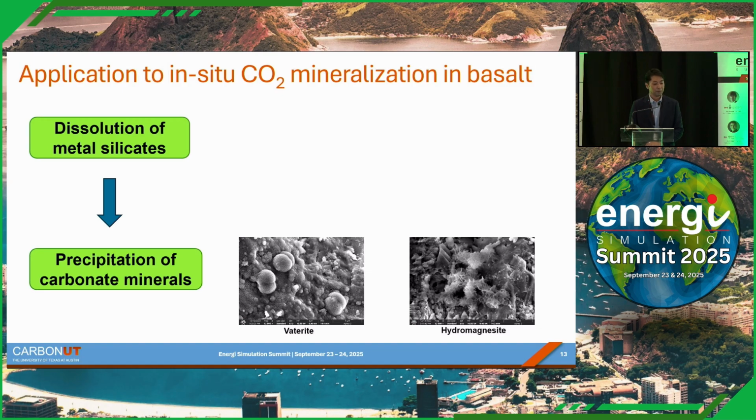The first step is dissolution of minerals that releases calcium and magnesium, those divalents that are going to be reacted with CO2. And the second step is precipitation of secondary carbonate minerals. This is where metal ions are going to react with carbonate originated from captured CO2.